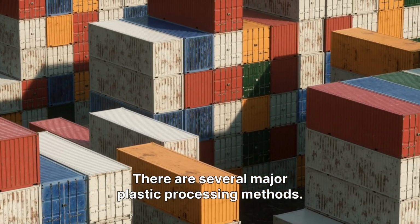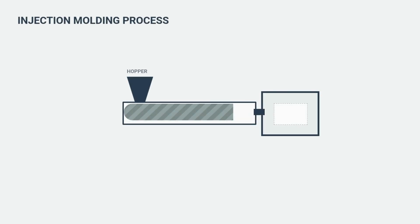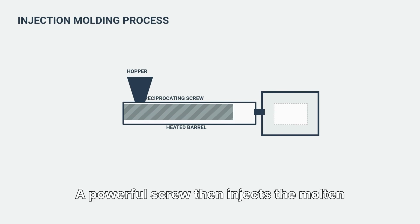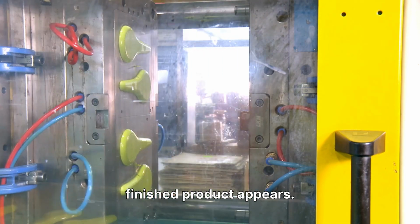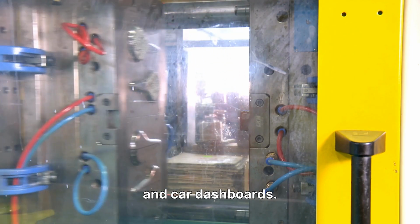There are several major plastic processing methods. Injection molding is the most common method. Plastic pellets are melted inside a heated barrel. A powerful screw then injects the molten plastic into a metal mold cavity. After cooling, the mold opens and a finished product appears. This produces mobile phone covers, bottle caps, and car dashboards.